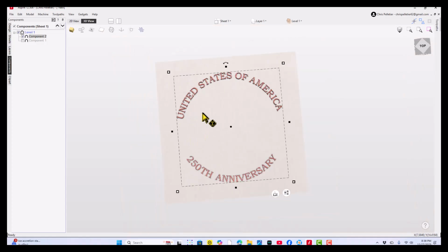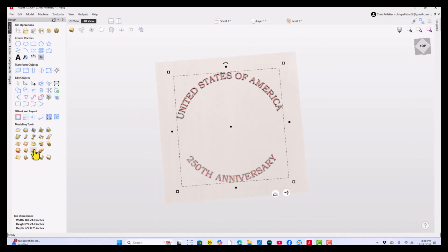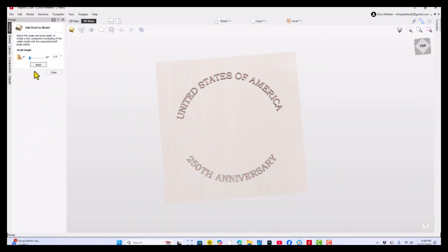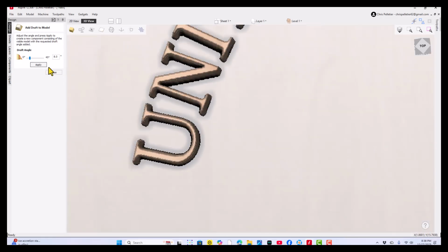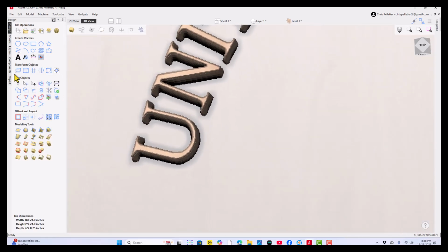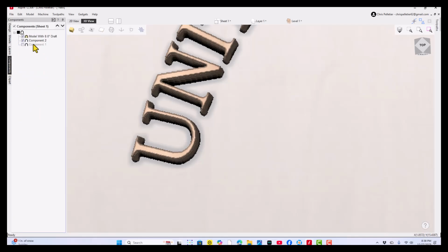You can only have what you want to draft on. Otherwise, everything gets drafted. So I'm going to select that, and I'm going to create a draft. I'm going to use 8%. Now watch what happens. We're going to get closer in, apply, boom.